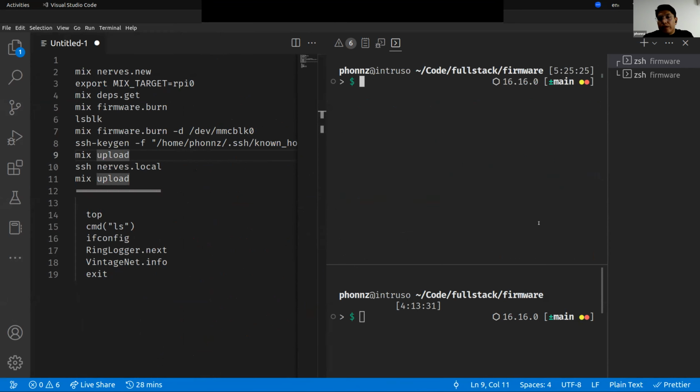When we want to build or compile something, we need to define the target. If we don't define the target that we are cross-compiling for, our toolchain will just take our host, the computer where we are working, and compile everything for this device. In this case, my laptop.